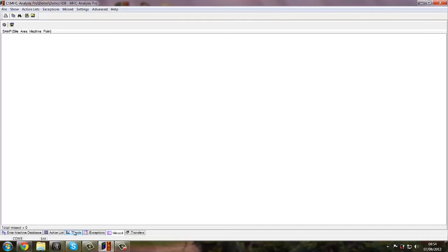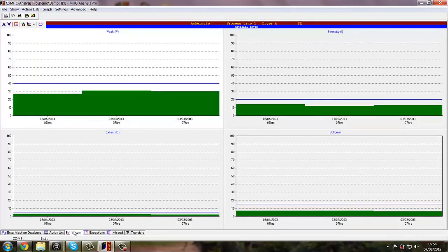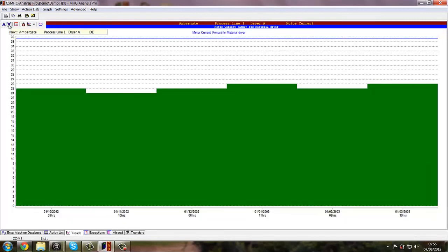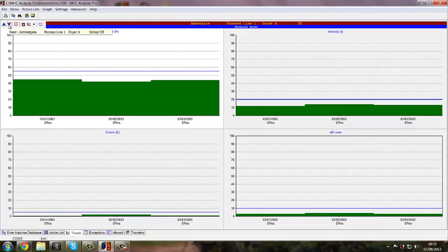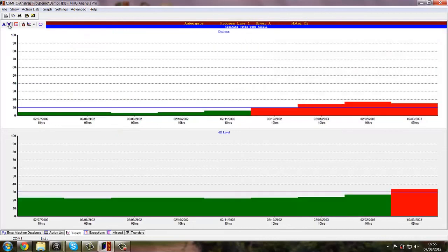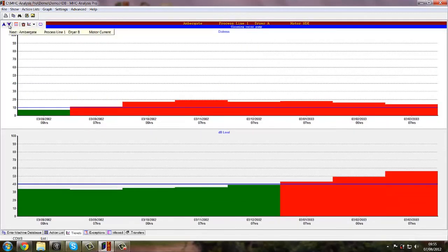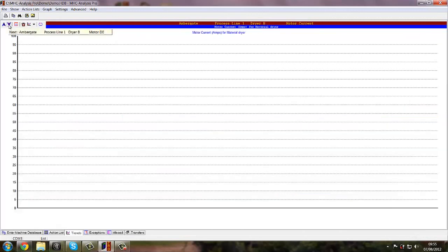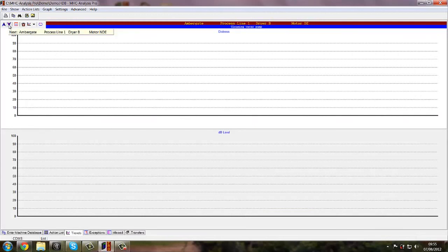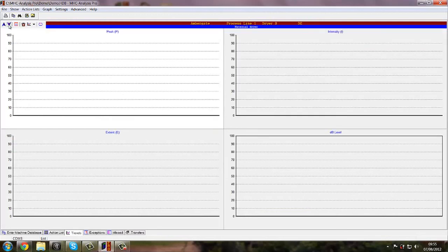Trends. Trends show the rate of degradation, which is by far the most important data to be gleaned by condition monitoring. This allows the user to decide if immediate action is required or during the next routine maintenance cycle. Store photos as a reminder of monitoring location. Photographs can be embedded in the software to allow reports to be generated and to allow users who are unfamiliar with the routes to know where to take the reading.